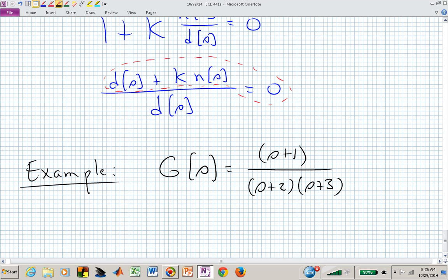So the question was, we are now examining that expression, d plus kn, and we're setting it equal to 0, and we're trying to find the values of s that make that happen. And we are going to adjust k, so we'll pick k equal to 1, and then solve that equation. We'll set k equal to 2. We're not doing that, we're virtually doing that. Now as we set k equal to 10 billion, which piece of that dominates or has the most impact?